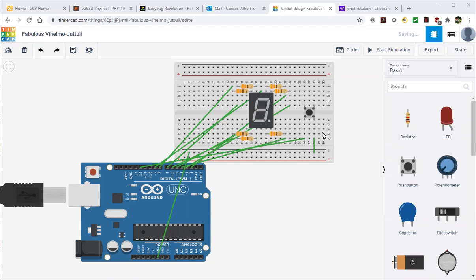In this video, we're going to talk about 7-segment LEDs, which you see right here. And we'll also talk more about arrays. All right, 7-segment LEDs, each one of these segments is a separate LED. And each one is assigned a letter. So this top one here is A, this is B. Next one down is C, D, E, F, and the one across is G.